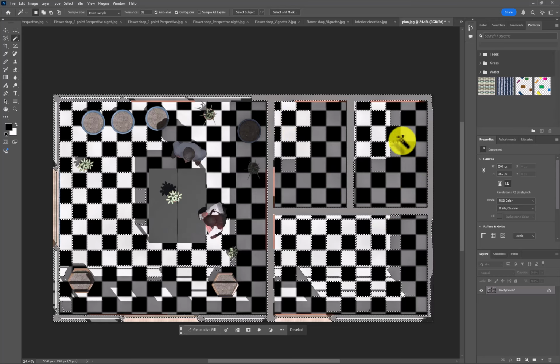You see how pretty quickly it can select almost all the gray, but it's also getting some boundaries of the flooring. Well, I can change the tolerance. Maybe I'll drop it way down because I really just want an exact match. Now when I click on it, I get it, but I'm still getting some weird little spots here.